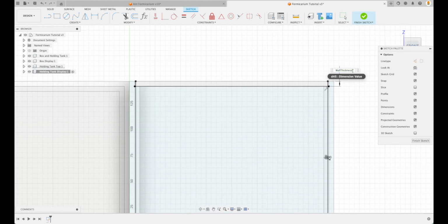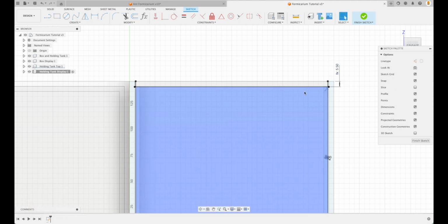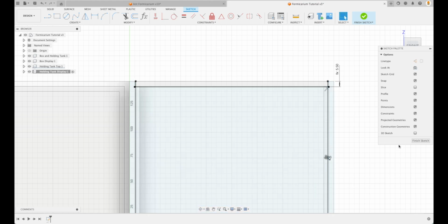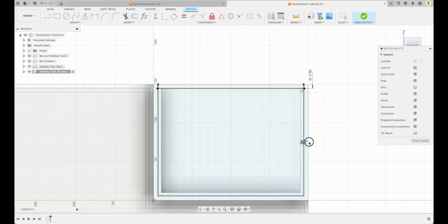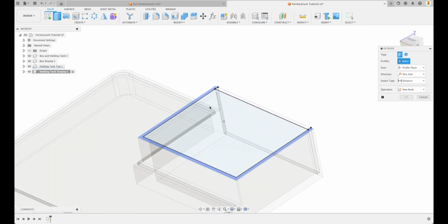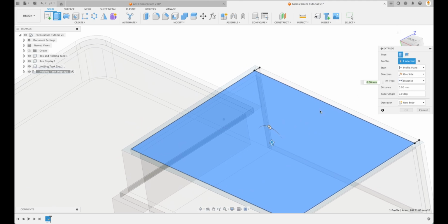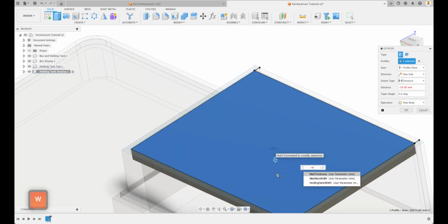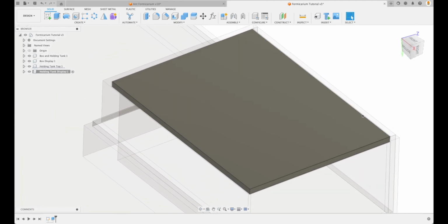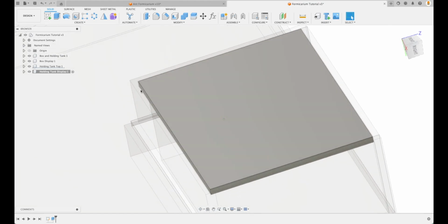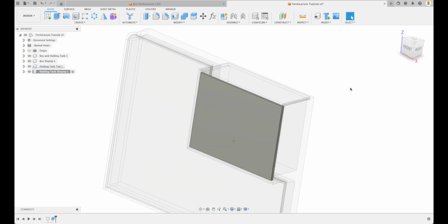So we're going to double click wall thickness plus relief. That's going to make it a little bit further from the edge there. And we're going to go OK. Oh, and I forgot to put in an actual value for this relief. This is only one mil, so we want to make sure to actually put a value there, relief. There we go. Now we can extrude it from there, and we're going to go in our wall thickness. Perfect. So now you can see there's this relief on all sides of our acrylic front display for that holding box. This is looking great.